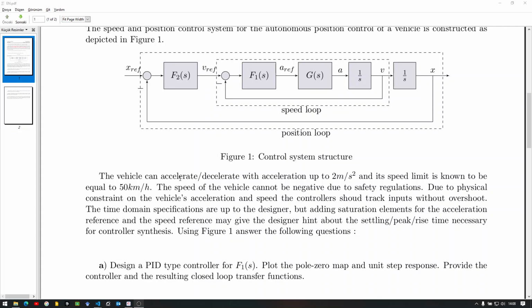So we're designing our controllers. Once we're satisfied with our controller synthesis, then we apply certain limits, because this is a real-world application inspired example, a case study. We know that the acceleration should be limited because we cannot infinitely accelerate, and you will see that hopefully if you look at that during your synthesis. Now, we can also not go up in speed to very high values. We have a limit here. So those limits are given. Negative speed is not allowed.